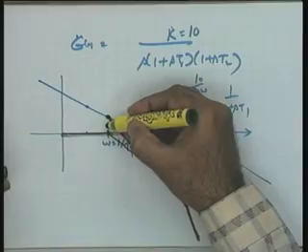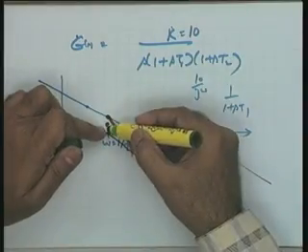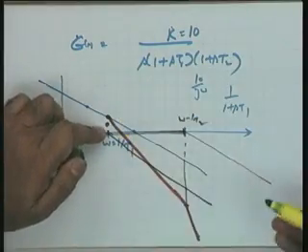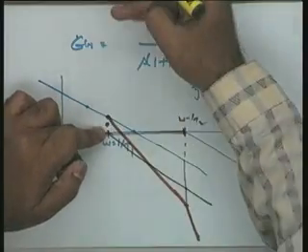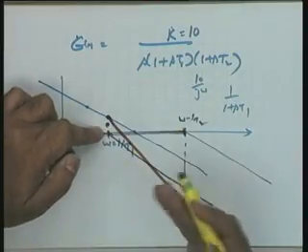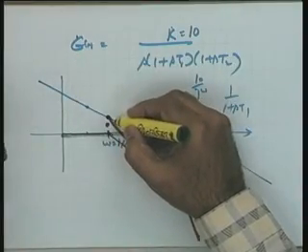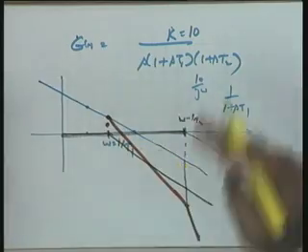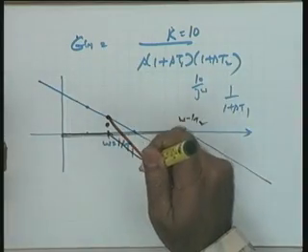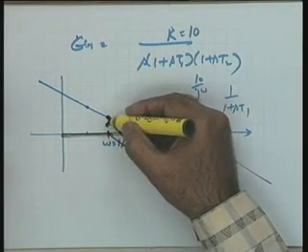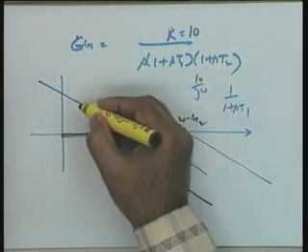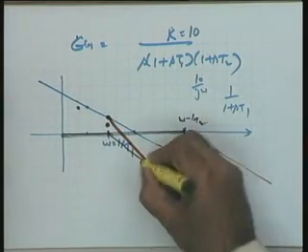Now, how about the approximations? The corrections can be made like this. Take the corner frequency, take a point 3 dB down. Why down? Because the slope changed by minus 20 dBs. If there was a change in the slope by plus 20 dBs, I would have taken this 3 dB up. So in this case it changes by minus 20 dBs. Now it is not the slope at this particular line, but whether this error will be up or down depends upon the net change at the corner frequency, whether it is with a negative sign or with a positive sign. In this particular case it is with a negative sign, so I take it down, and here 1 dB, 1 octave below is here and 1 octave above is here.